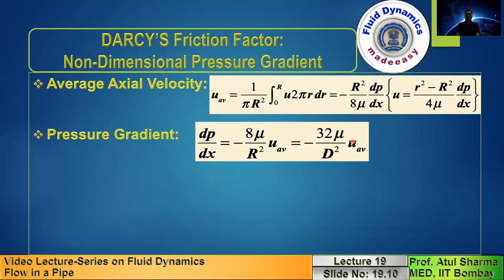As I mentioned in my previous topic on differential analysis, towards the end I had a topic on non-dimensional study where I had emphasized that in fluid mechanics we present our results in a non-dimensional form. So the two engineering parameters which are of importance for flow in a pipe once the flow reaches a fully developed situation are the pressure gradient and the wall shear stress.